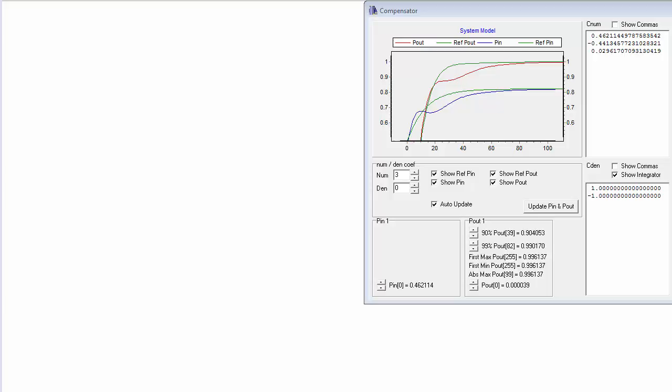A step input is supplied to the plant and the response is measured. The characterization data is imported into a PC tool that computes the system model. Next, the plant input is shaped and massaged until we are satisfied with the plant input and output. In this case study, we'll keep it simple and use an exponential plant input.